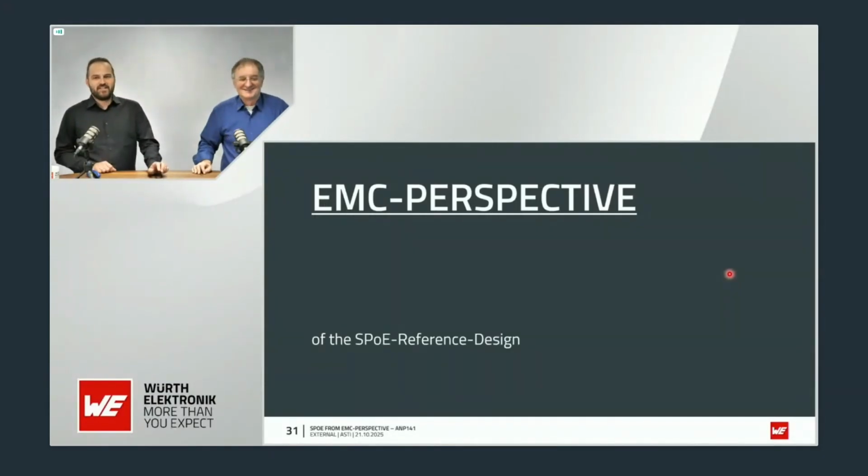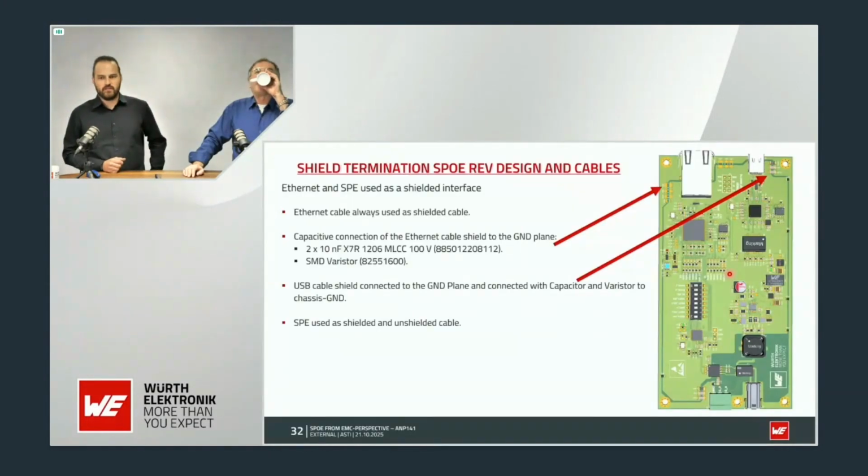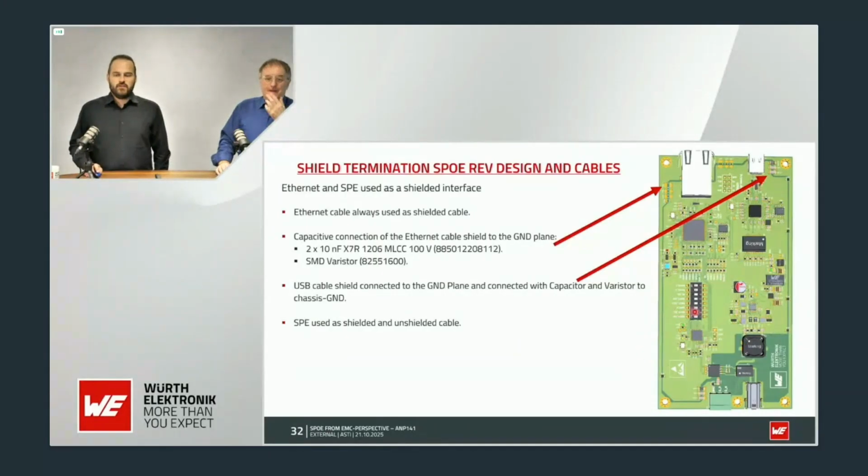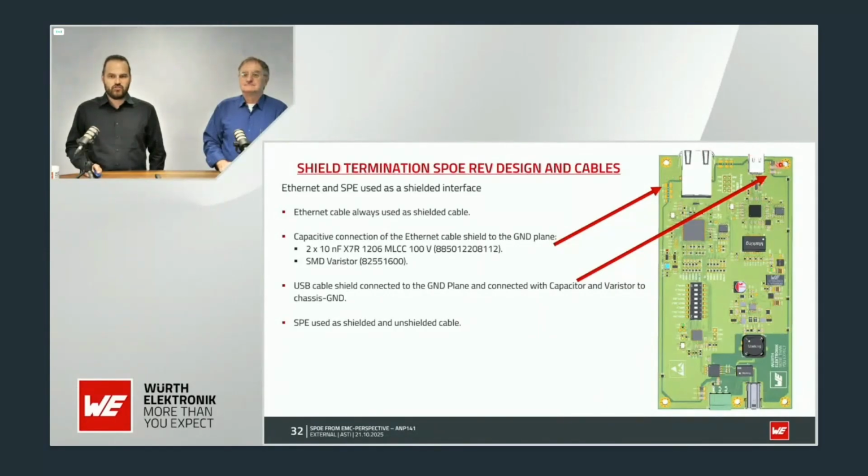So then let's have a look at the EMC performance of this reference design. Since we are limited in time, we will focus on the emissions and immunity. A quick overview first of the boards. As Heinz mentioned, we have two different grounds. You have the shield ground where we can connect the shields, and we have the digital ground.